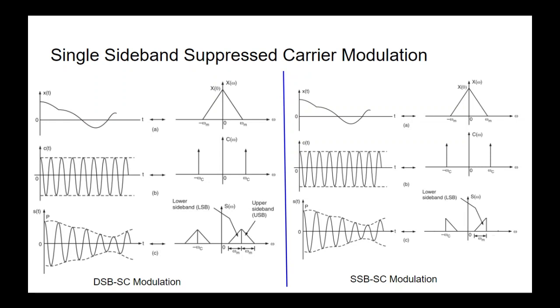So we are transmitting the information with the help of two sidebands, upper sideband and lower sideband, and both sidebands are identical. So we can transmit our information with a single sideband, as both are identical, so we don't need both sidebands. We can convey the information by a single sideband. So we will suppress one sideband to make it further power efficient. In the right hand side figure you will find that we suppress the upper sideband and we are only transmitting the lower sideband.